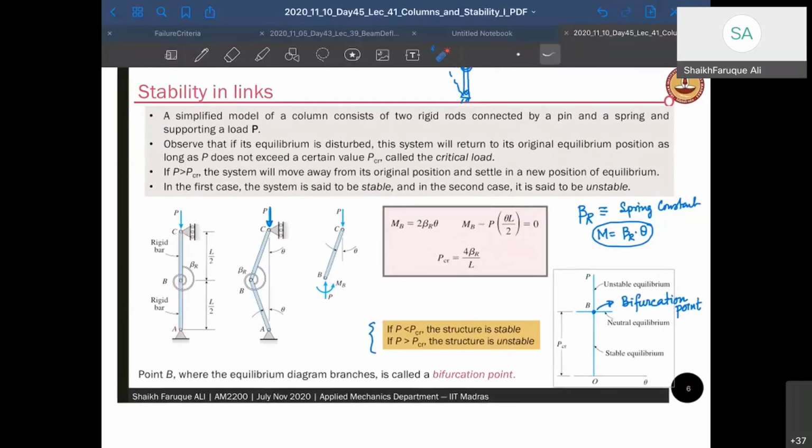Okay, it is linked at point B, and there is a spring force at point B, or torsional spring, or rotational spring. The upper part of the bar CB is rigid. Below part of the bar AB is also rigid. So when I say rigid, that means they make an angle theta like this, and that angle theta is constant all through, right? So it is not bending like a beam. It's like a rigid rod.